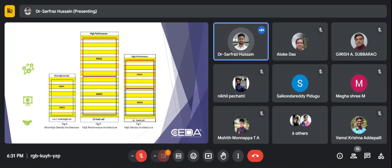So this is how we actually design the standard cell. You can go for an ultra high density standard cell, or you can go for a high performance standard cell. In the high performance or high density architecture, you can see how it differs. For high performance, we need a larger space. If you want high density, it means you have to reduce the size. There is a 7-track high cell and there is a 12-track. If you want ultra high density, you have to bring it to 6 or 7-track height. So this is how the standard cell looks, and you have a VDD and this.